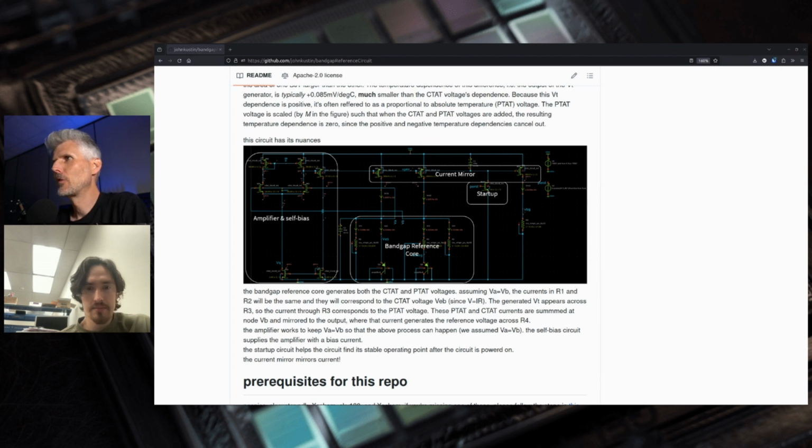Okay. And then we've got what looks like an op-amp circuit to me up on the left-hand side here. It looks like a fairly classic differential pair and current mirror. Right. Yeah, that was a tricky part for me of starting out. This was the first circuit I'd really ever designed. And the amplifier, from a top-down view, is doing a good job if the two voltages VA and VB are approximately the same. That condition is in the derivation of how this bandgap works and what the output voltage is. This VA equals VB is a critical assumption that you have to make.